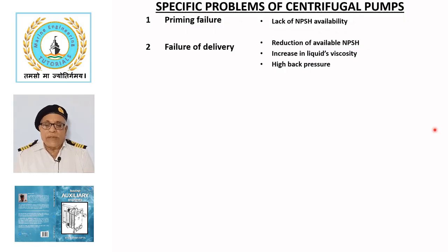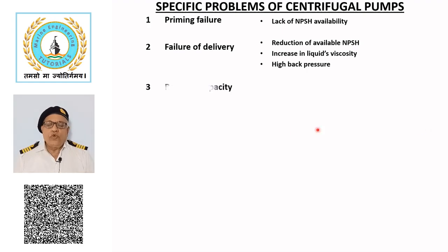If the total head exceeds pump design head, a booster pump will be required in the delivery line. In case total head is less than design head, the problem is caused due to reduced capacity and the pump will require overhauling.